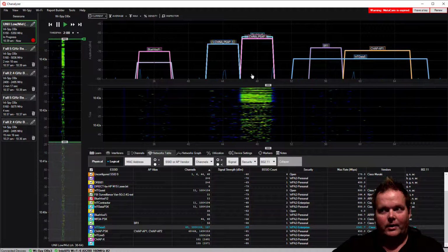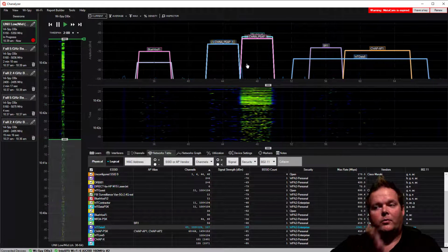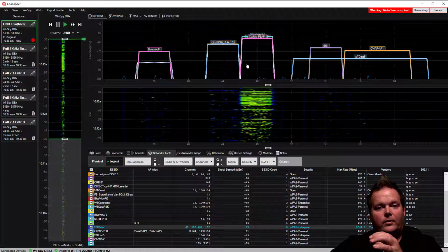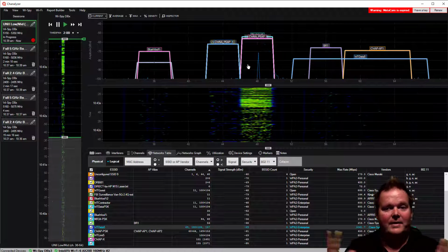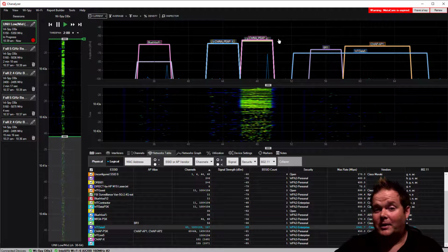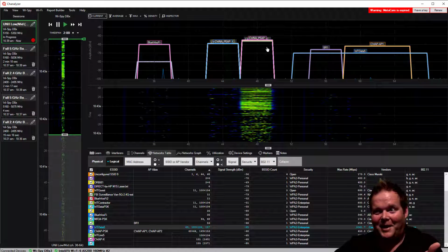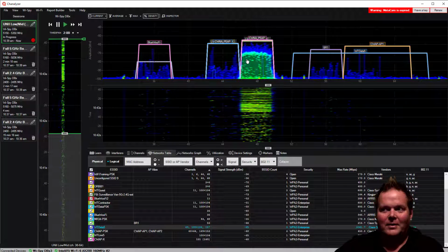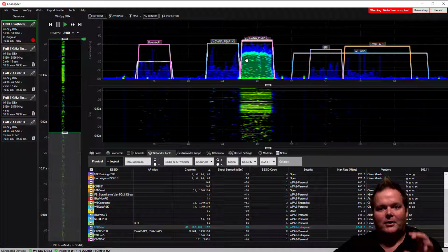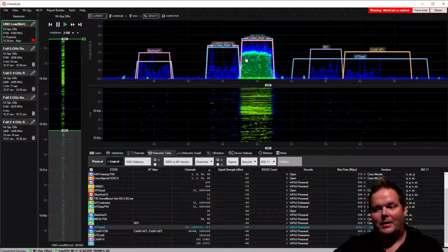You can see right now, this is why the resolution is not important with spectrum analysis. It's nice to see stuff blazingly fast, but it happens so fast you really can't see. There's no way we could sit there and watch the modulation happen in real time. So we've got to look at that density view. But bottom line, that's what it looks like whenever a channel starts getting utilized in an area. Okay.